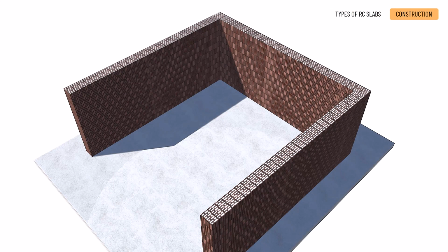Modern execution of monolithic reinforced concrete slabs. The four important steps in the construction process are formwork, reinforcement, concreting, and removal of the formwork. Formwork. In modern practice, we use large formwork sheets with timber beams which allow the formwork to be assembled quickly.